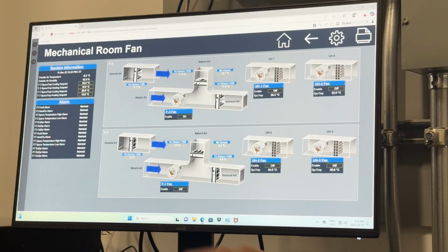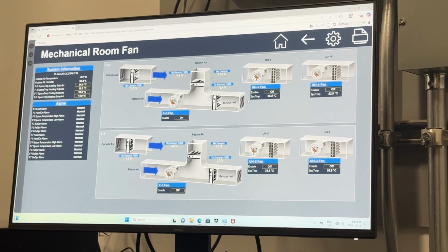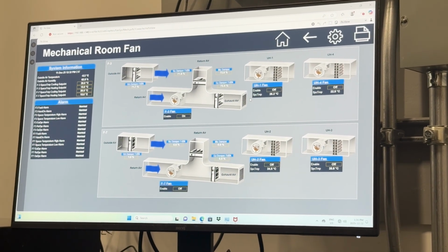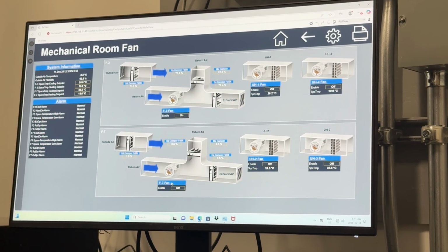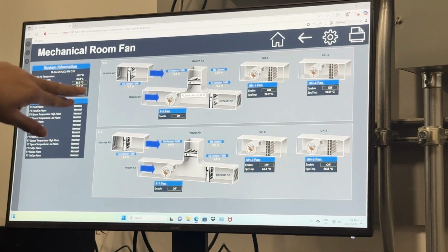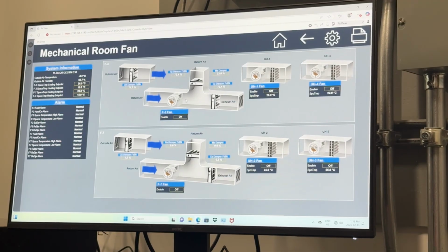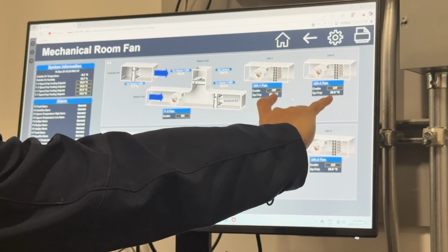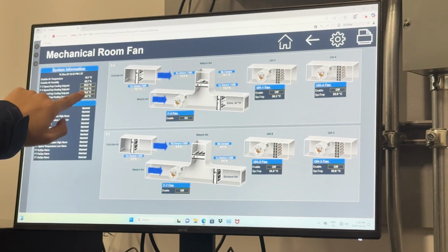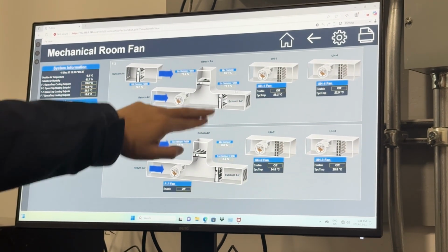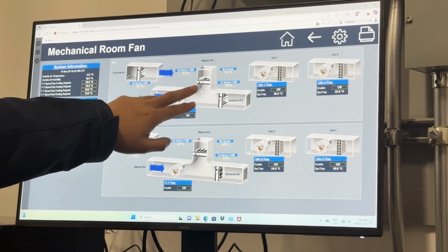This is actually where we are, it's in here. Maybe let me finish this, and I will show you where these things are. We have two fans, fan 3 and fan 7. Fan 3 will turn on to reject the heat. For example, when the average of those two space temperatures reaches 26, the exhaust fan will turn on.